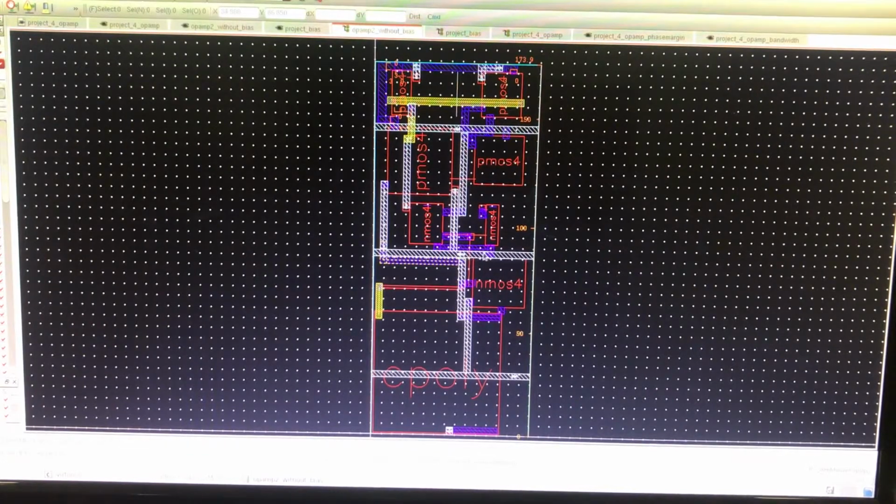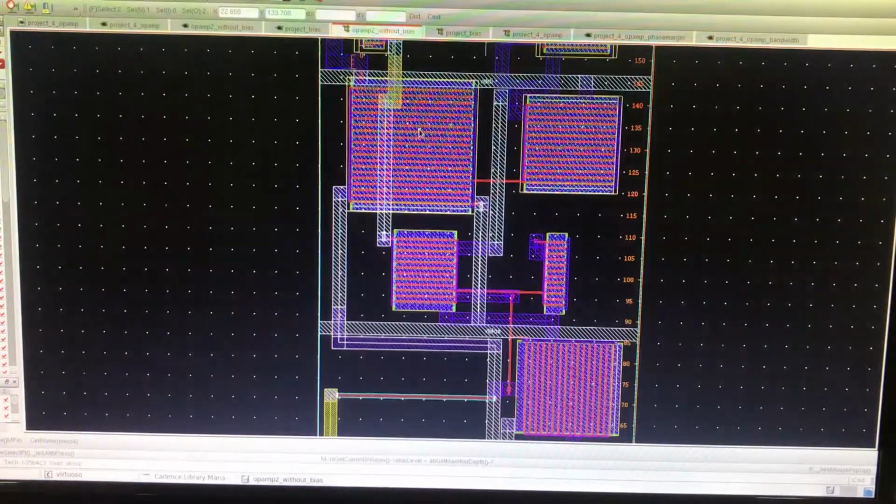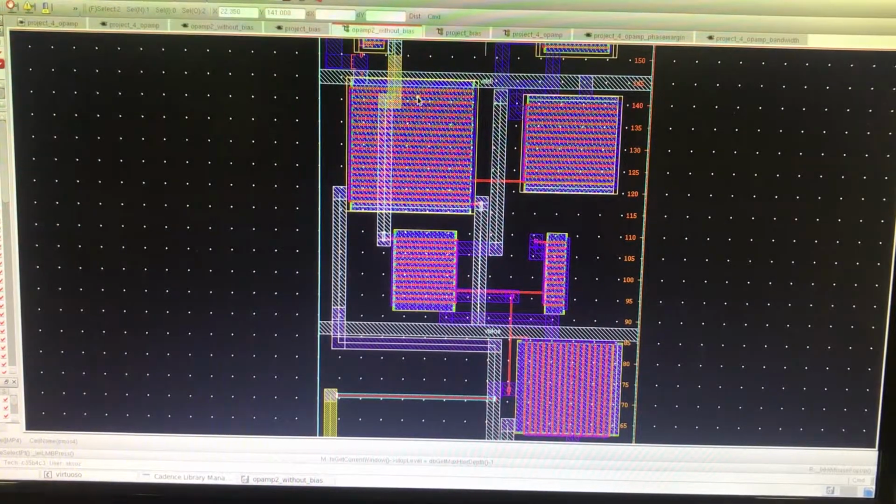You can also see the routes driven by myself and by doing auto-routing. Some parts aren't drawn by the auto-routing of Cadence, so I have drawn them by hand. And I have also adjusted the number of gates of transistors to have square-shaped transistors for ease of easily putting them inside the layout.